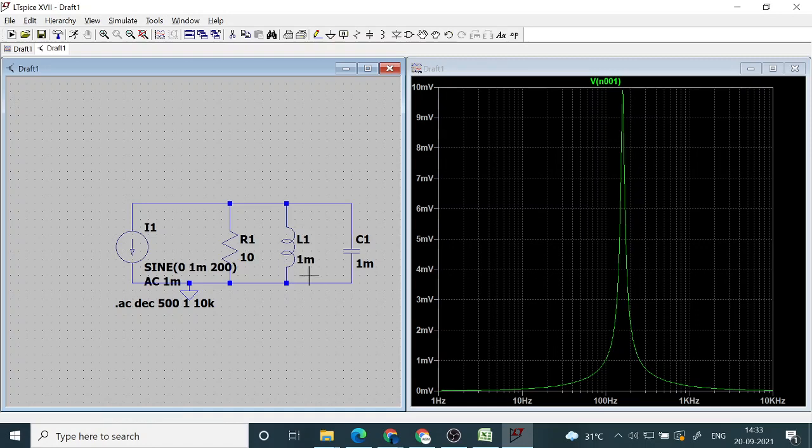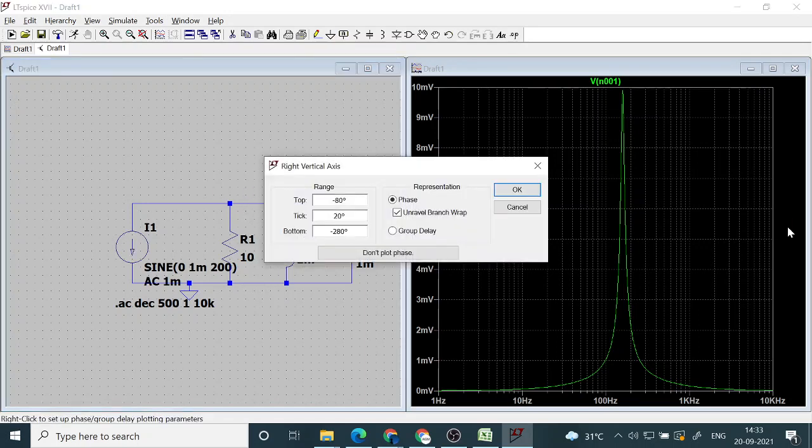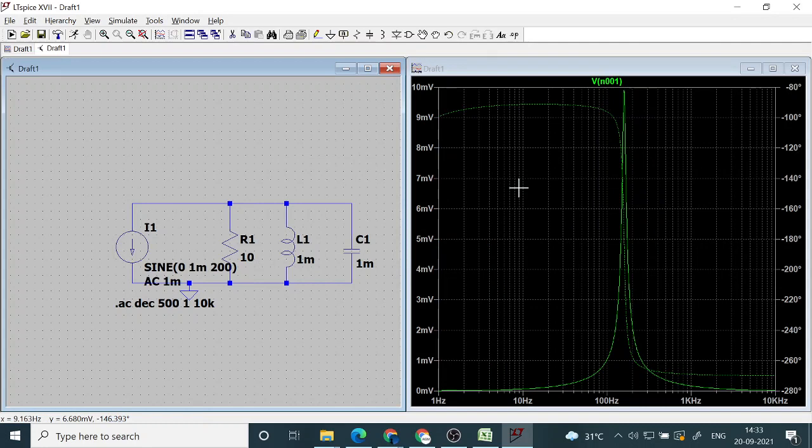Okay, but somewhere in the middle, capacitor and inductor, their impedance will cancel each other, or you can say admittance will be, one will be plus, another will be minus, both are same magnitude, so they will cancel each other, and effectively it is resistive. And you will see, if it is resistive, the current and voltage will be in phase also. If you bring phase into the picture,